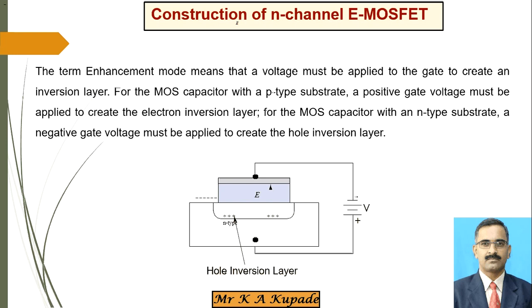And the inversion layer that is considered has some positive charge, so that plate acts as the positive charge, and the other, the diffused area, acts as the negative. So these two plates act as the capacitor. This kind of construction is called a MOS capacitor, right?